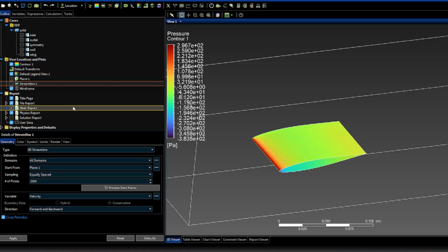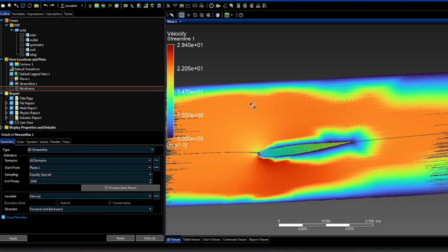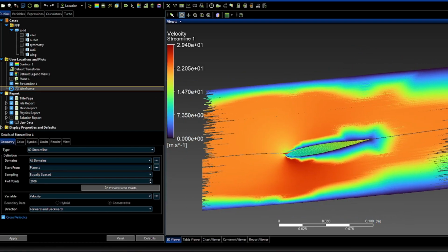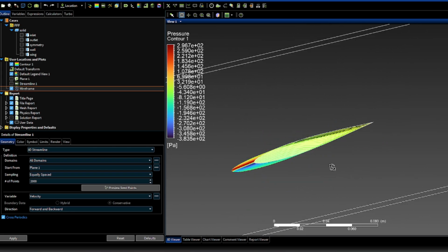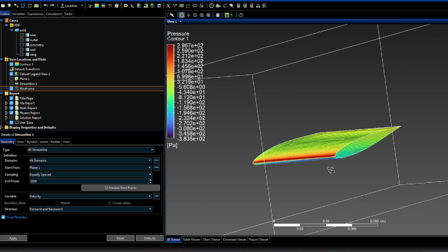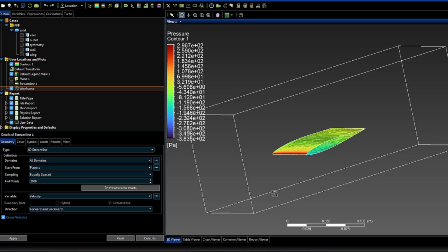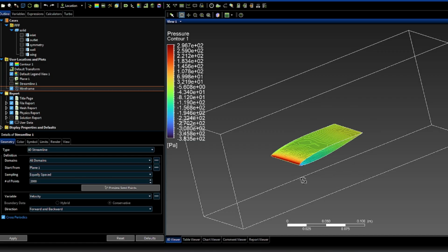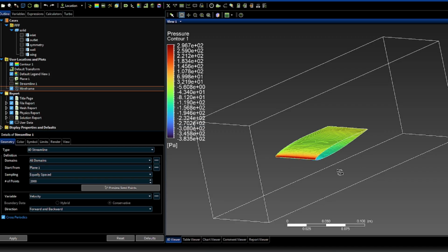I haven't explained too much on the result. You can see many types of things and many types of calculations, but these are the simplest things that you can do on Ansys, and it's so useful for making wings, for making your model, to know how much downforce you need or how much lift you have to have, how your model tricks the air during all the process, the speed of the air, where it generates vortex, how much drag it generates. So this is the tutorial.